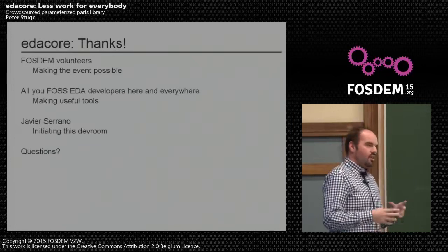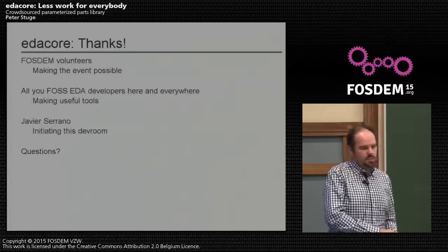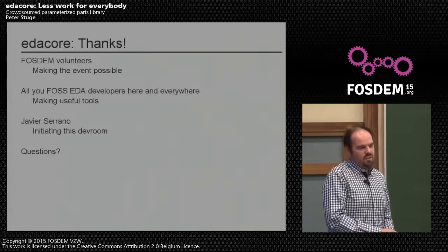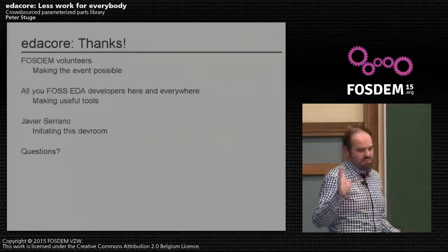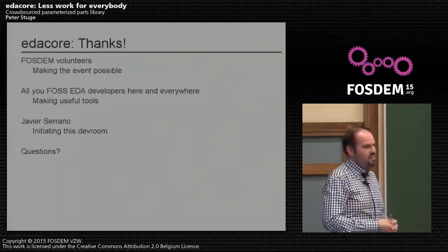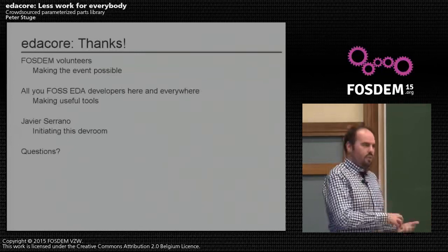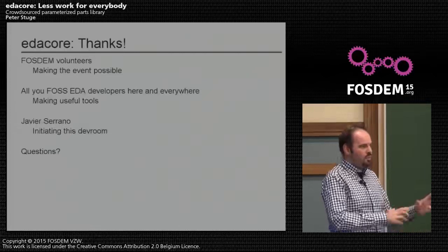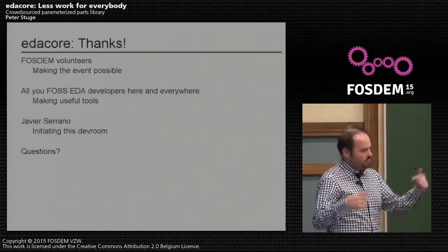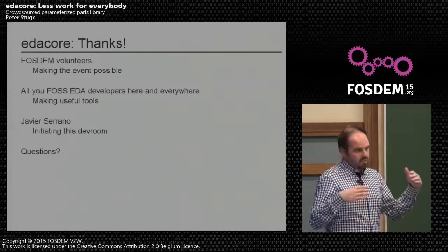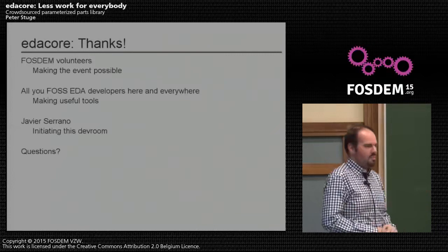The important thing is that these should all at the very least belong to the particular circuit, the particular chip that they are for. Let's start there, because at the moment they don't. At the moment it's just a flat namespace of lots of different parts. Baby steps: associating different footprints with one particular part, so that at least the symbol stays the same, or there are 2 variations of the symbol and 4 variations of the footprint, and I can choose which combinations I like, but it's still the same logical part. That is something I'm looking for.